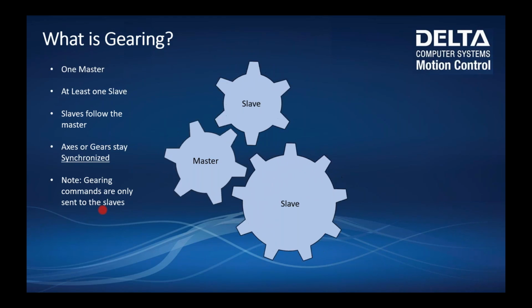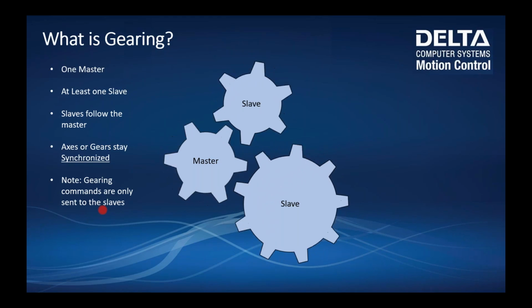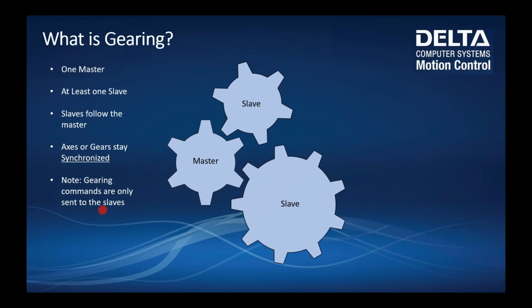If you're trying to set something up, you may think, well, I need to send a separate command to the slaves and another one to the master. But actually, you'll only need to send these gearing commands to the slaves. The master will just continue to move as if nothing happened, really. And unless you set up a halt to make sure that everything stops when one of them stops, this master will just keep moving. It really doesn't know that other axes are geared to it.